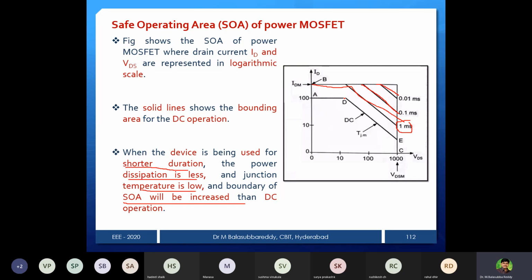The difference is very simple. While you are doing a load test of a machine, if you load it more and run the machine for a long duration, that's why in our load tests we use water and a pulley. We pour some water on the pulley. Why use water there? Because you are operating the machine for a long duration, power dissipation takes place in the form of temperature rise, and heat will be developed in the armature winding. To cool that, we use water, just for cooling purposes. But if you fully load or even overload it for a fraction of 1 minute or 1 second, it won't happen, so it will be allowable.